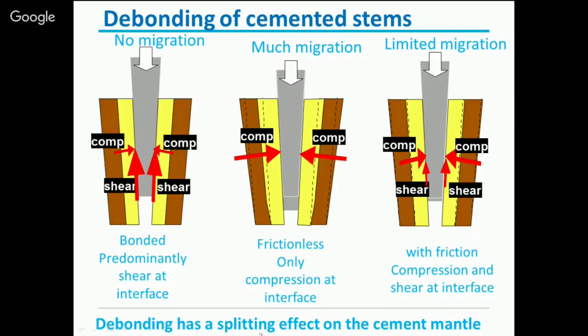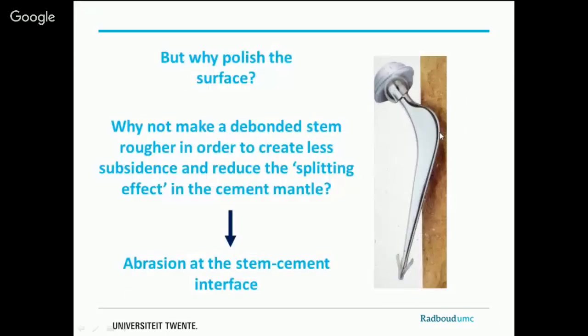So debonding has a splitting effect on the cement mantle. You can imagine if this is forced lower and lower, it will crack the cement. It will open up the cement.